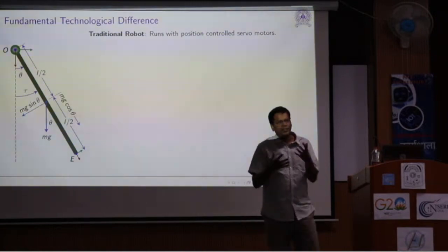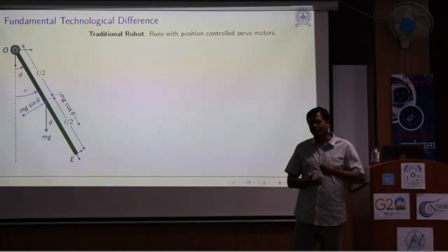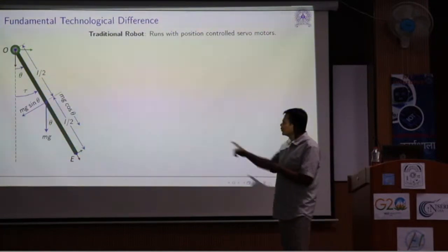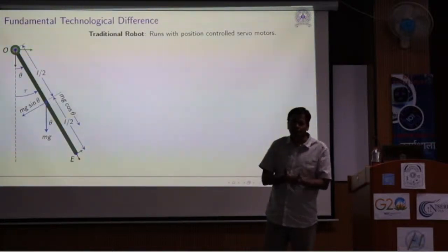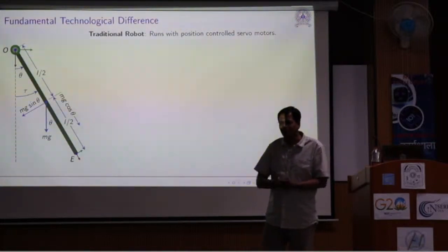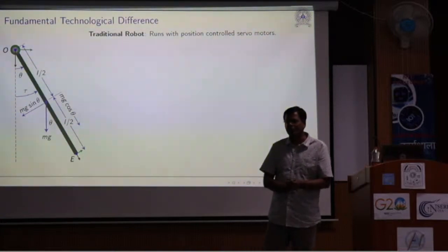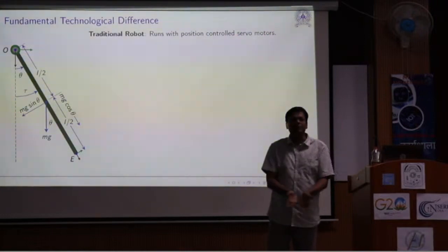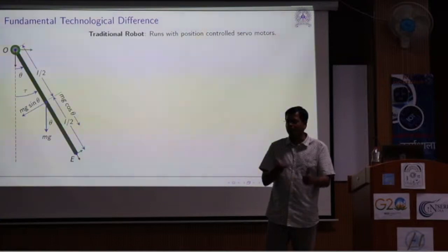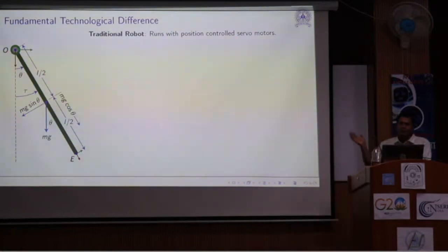So it should have a complete model of the system, including the moment of inertia. It not just includes the static torque in its model, it also includes the dynamic torque, it also includes the state of the robot, many other things. Finally, it freezes its torque. When it is driving the robot with that particular torque, it has complete information about the robot. Robot moment of inertia, robot statics, right? Complete detail. Okay? So you need a complete knowledge when you make a cobot.